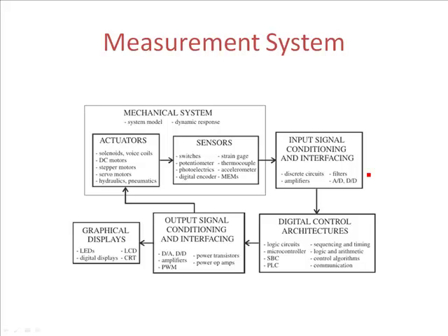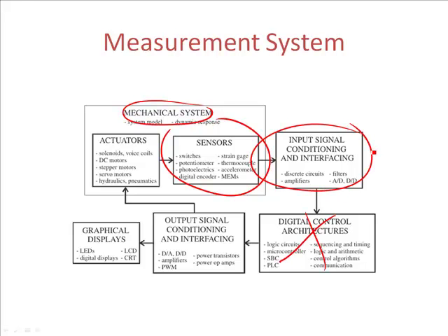Now, a measurement system is not the same as a mechatronic system. Most mechatronic systems do have measurement systems, but sometimes we might want to have a standalone measurement system. This is when we might be troubleshooting a part of the system out in the field. In that case, we basically just have the mechanical system with a sensor and some electronics, and now instead of trying to control it, we're going to have some way to measure that output. And so that's where the recording device comes in, whether that's some kind of a meter, an oscilloscope, it could be a paper tape,